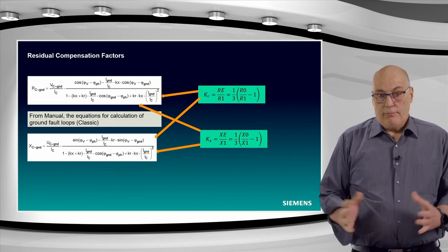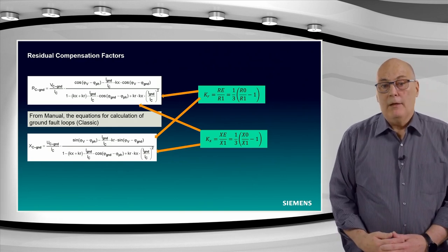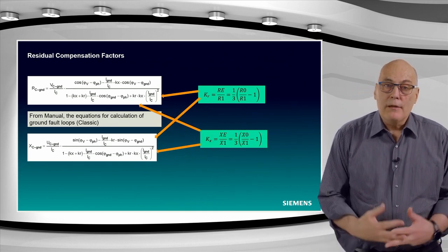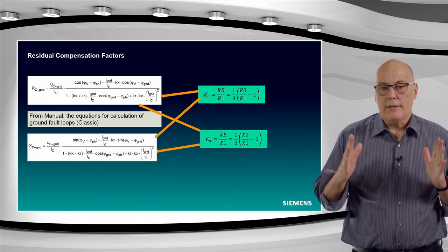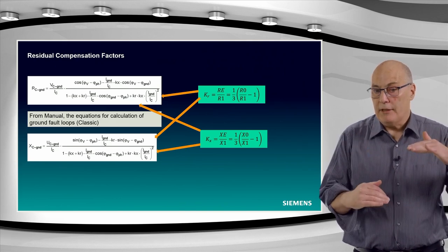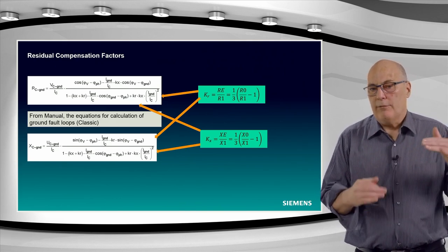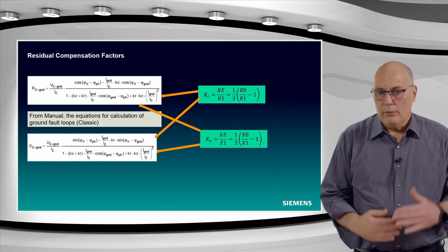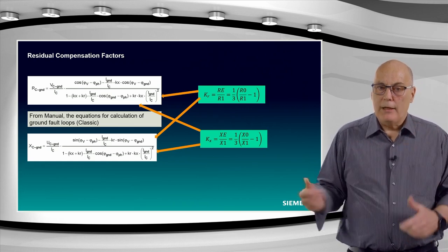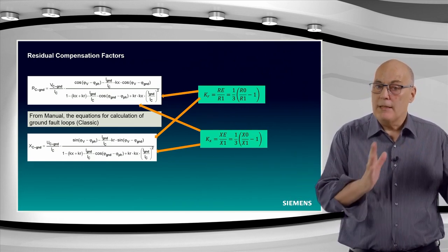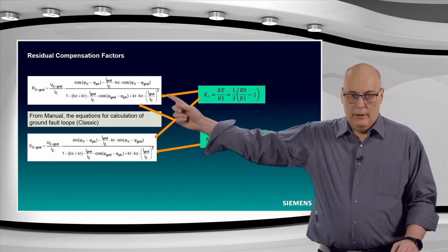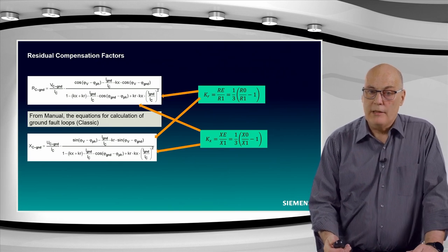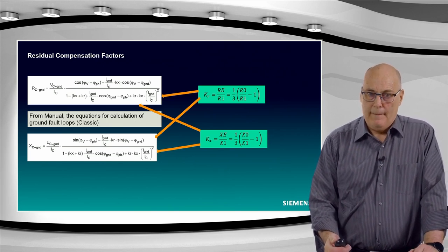Why do you use this rather intricate method? Because on the left-hand side of these two equations, what you see there, the measured impedance is the positive sequence impedance. So we can apply the same reach setting. Well, later on we'll apply reach settings, and we then no longer discuss whether it is for a ground fault or a phase-to-phase fault. It doesn't matter, because both the phase-to-phase faults and the phase-to-ground faults will measure an impedance which is basically the same. It is the positive sequence impedance, or as shown here, the loop impedance. And we can therefore apply the reach settings based on positive sequence impedance.